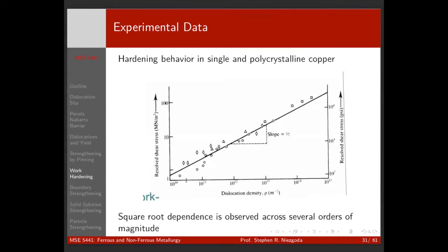A huge amount. What about the other extreme end? What's the most that we can really physically pack in? If you do shock loading at cryogenic temperatures, what kind of dislocation densities can you come up with? Well, this chart goes up to 10 to the 15th.